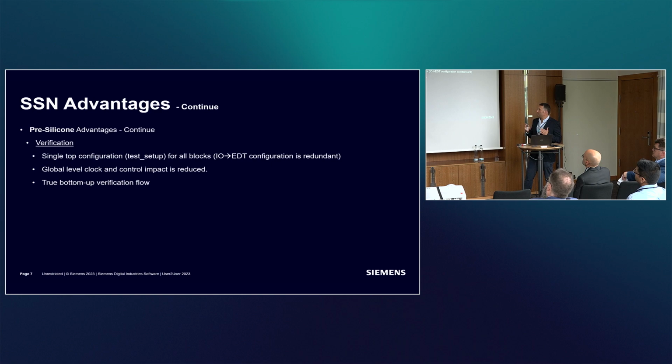As I mentioned, the controls and the clocks are no longer generated from the IOs, so they're not global anymore. That's really easy for the verification, so we don't need any top-level GLS with SDFs. It's really going to be handled internally, and that's really a bottom-up verification flow.